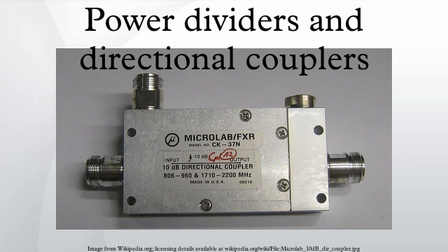Transmission line types. Directional couplers: coupled transmission lines. The most common form of directional coupler is a pair of coupled transmission lines. They can be realized in a number of technologies including coaxial and the planar technologies. An implementation in stripline of a quarter wavelength directional coupler is shown in Figure 4. The power on the coupled line flows in the opposite direction to the power on the main line, hence the port arrangement is not the same as shown in Figure 1, but the numbering remains the same. For this reason it is sometimes called a backward coupler.